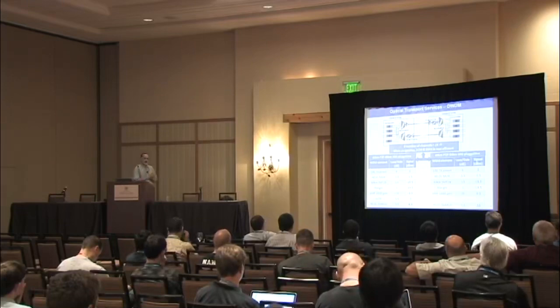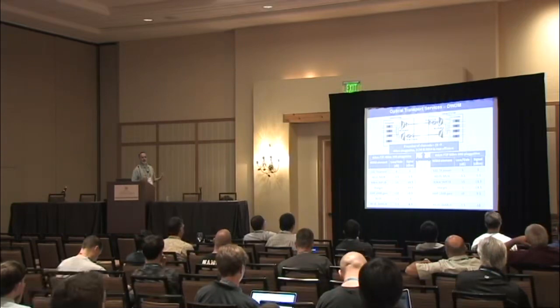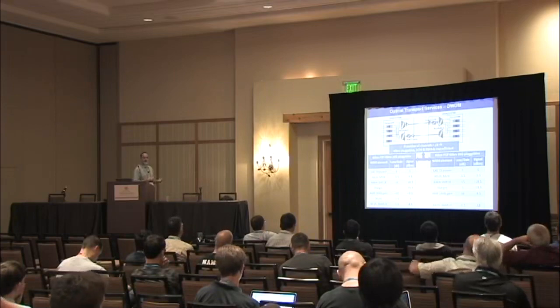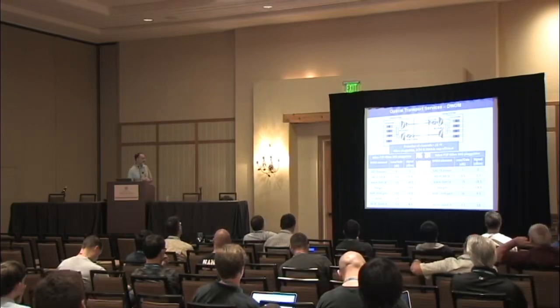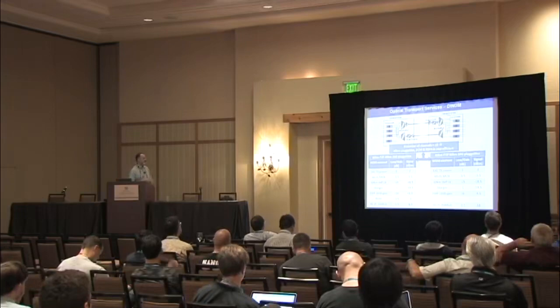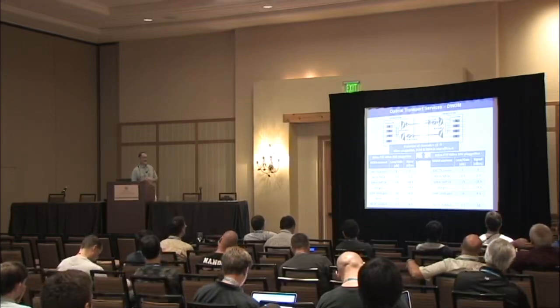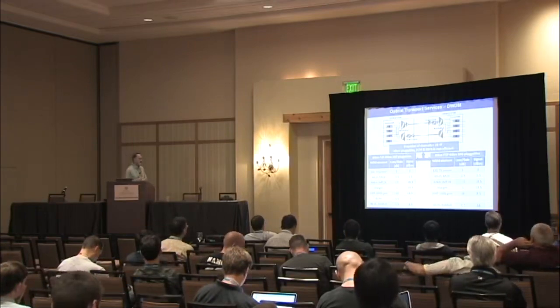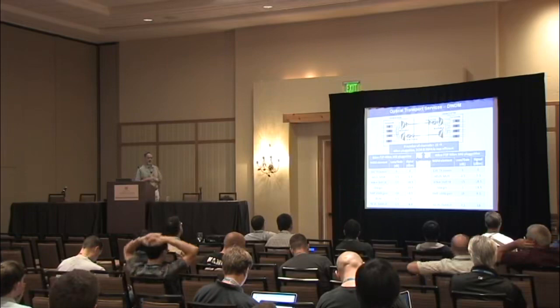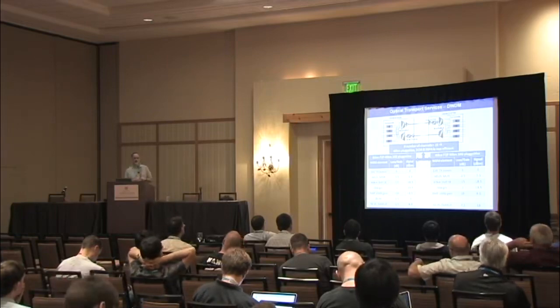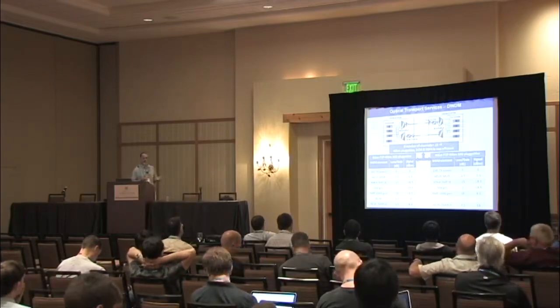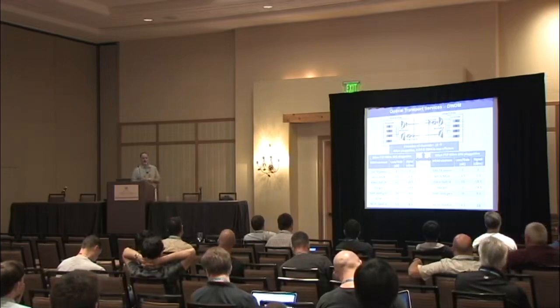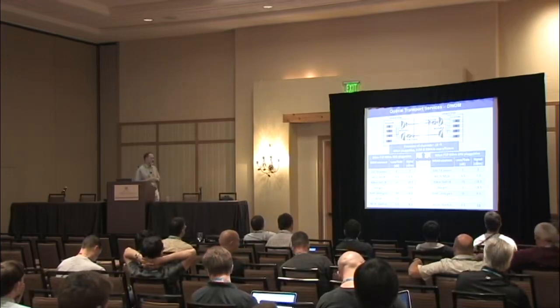Let's do 60 kilometers, and what's the change here? With 60 kilometers and 40 kilometer optics, I'm not going to have enough dispersion tolerance. So I need to add not just amplification, but also dispersion compensation. If you go over the chart, it's basically the same. The transmit power is at 0. The 40 channel Mux adds minus 3.5. Then 60 kilometers of fiber is minus 15. I'm putting in a margin of minus 1 dB, and I'm at minus 19.5, well outside the range of the 40 kilometer transceiver.